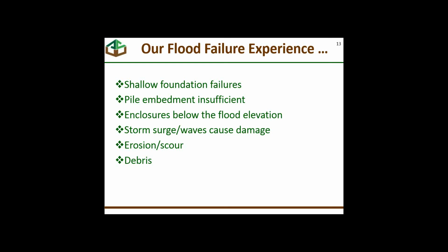But once those waves get high enough to actually slam into the wall, and it's only got to be 6 inches to a foot, then there can be a lot of damage. Erosion and scour occurs frequently. We have to design the loss of soil into the design for a new foundation. And then I've already mentioned the issue with floodborne debris, and then the importance about at least thinking about and planning for that debris.